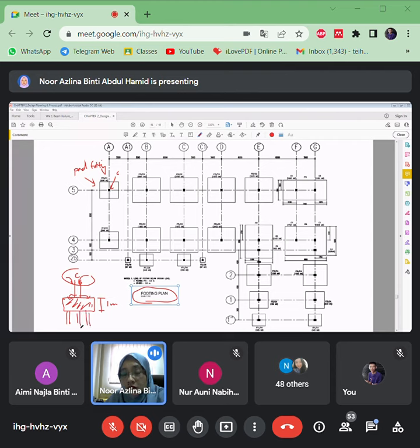It depends on the number of pilings. It also depends on how much load is applied on this point here. If the loading is not very high, it might be just two piles. It also depends on the depth of the footing and the piling here. Okay, if you look here, there are different sizes. This one is smaller, this pad footing is a bit bigger. Actually it depends on the load on this column.